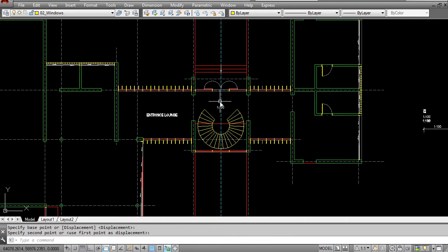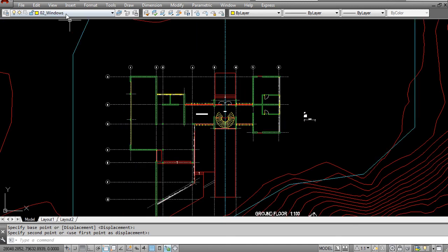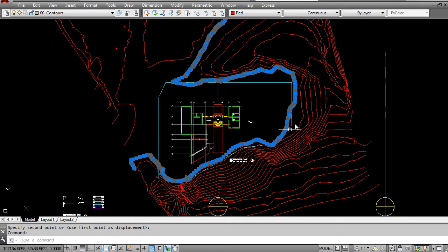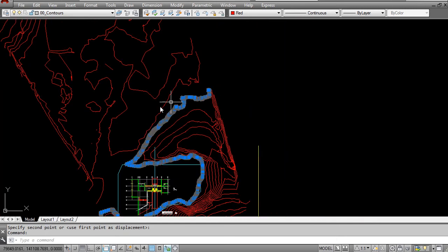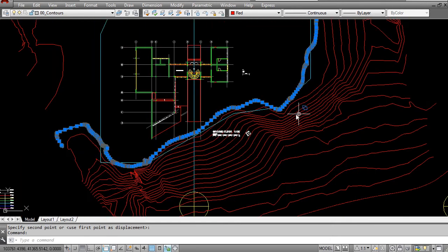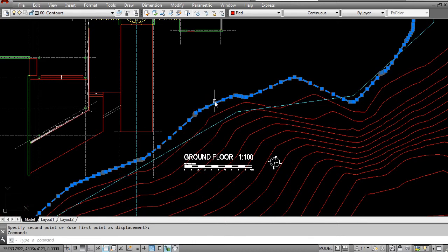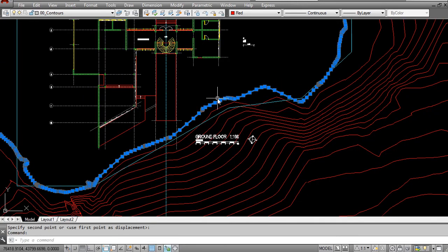And what that is going to be based on is either a figure which is above sea level, if you are aware of what those figures are, or if you're really far away from the ocean, you can always, in any case, use a datum point that you decide. So let's say we have our contours and we decide that this contour, which is, I don't know what height right now, but we can work that out, is going to be our 0 point. So this in reality, in above sea level terms, could be 16 meters above sea level, for example.